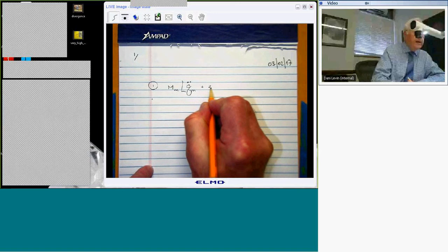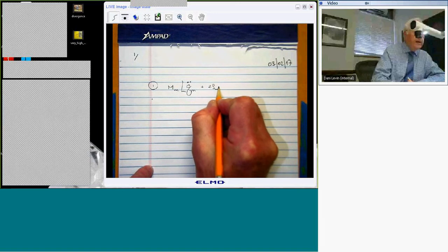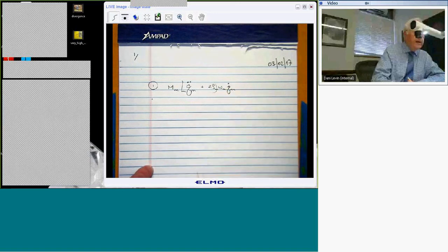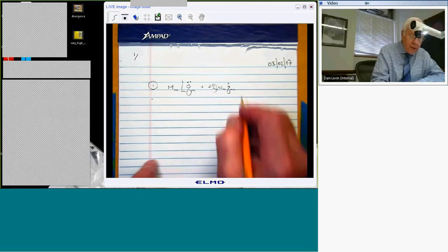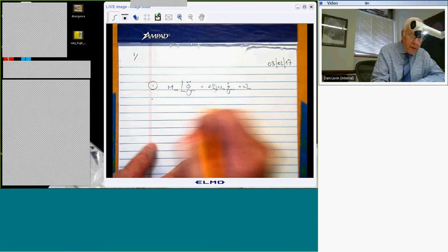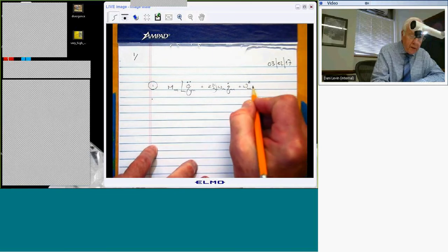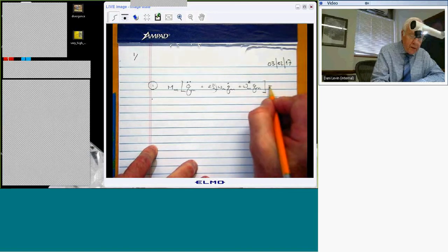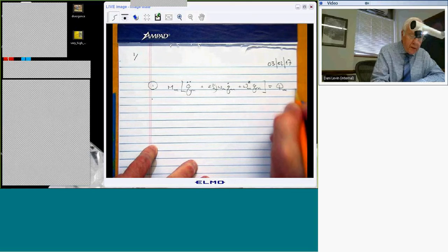Here's the inertia term. Here's the damping term, where the zetas are made up entirely based on vast experience or not so vast experience, plus the stiffness term, which for linear elastic systems can always be expressed in this way, which is quite remarkable if you think about it, equal to a generalized force.